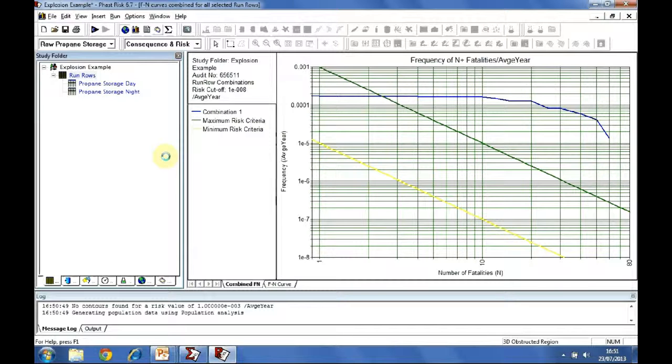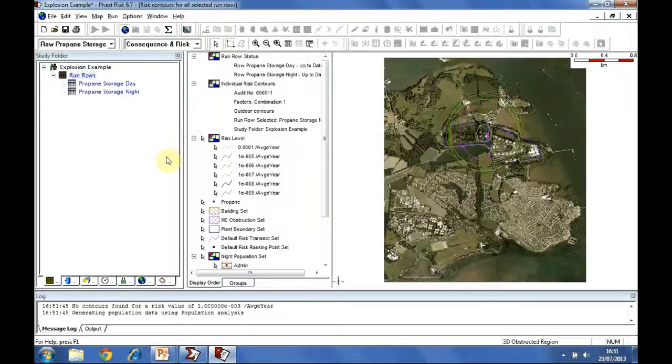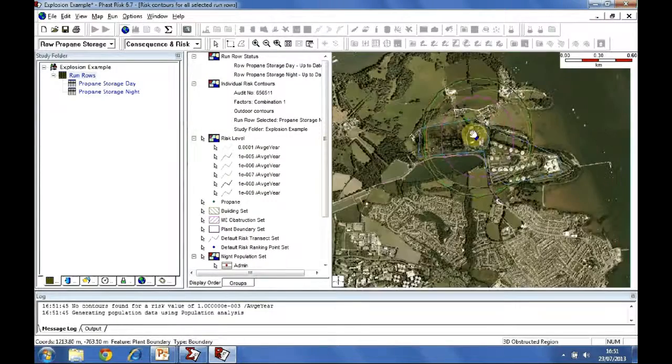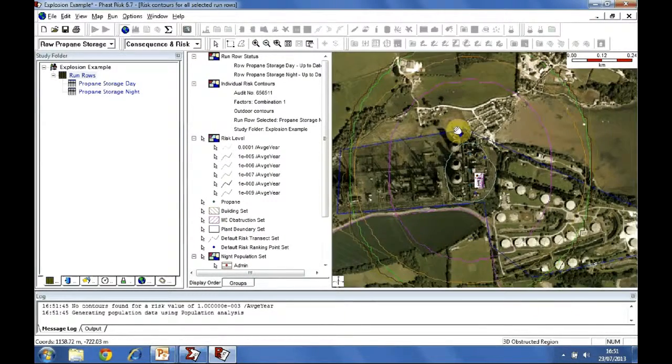And of course this is by default taking account of all of the potential hazards, so jet fires, fireballs, pool fires, toxic impact, things like that, depending on the inputs to your case. And you see the results as a series of ISO lines through effectively a risk array, so a set of risk contours around your plant. Now, to account for the more complex calculations that are performed using the 3D explosion method, a new reporting format has been produced.